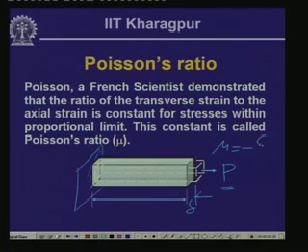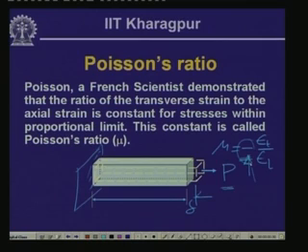So far as the definition of Poisson's ratio is concerned, it is the ratio of the lateral strain to the longitudinal strain. And if you remember, we had designated this mu as minus the transverse strain to the longitudinal strain. And remember that we had put this particular sign as negative, because when this is being pulled by an axially tensile pull, then there is contraction on other sides, and this negative sign indicates that there is contraction. Similarly, if this particular bar is subjected to an axial compressive force, where the length in the axial direction is going to shorten, thereby the other two directions it is going to increase, and eventually that shortening of the axial length is being designated as negative to the expansion of the other two sides, and that is why this negative sign comes in.